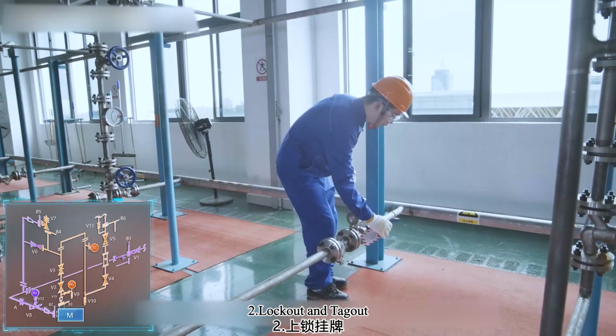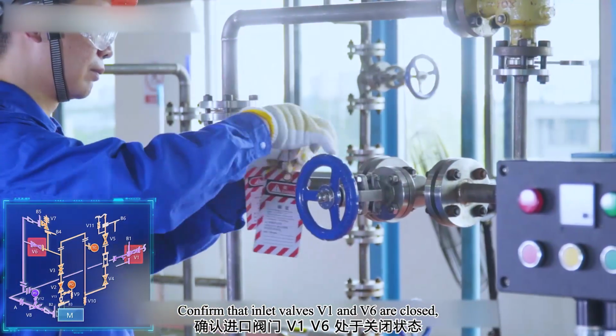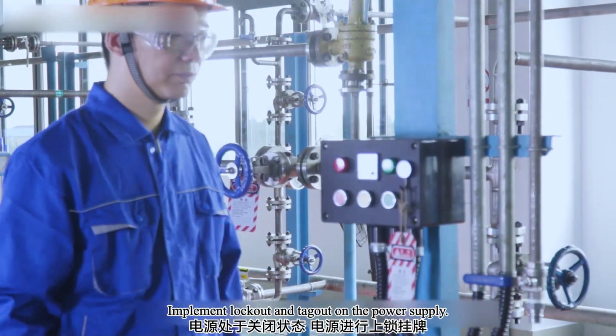Second, lockout and tagout. Confirm that inlet valves V1 and V6 are closed and the power supply is turned off. Implement lockout and tagout on the power supply.